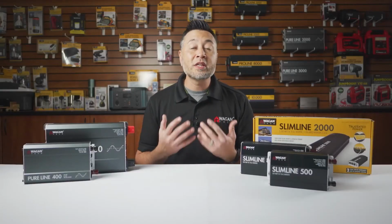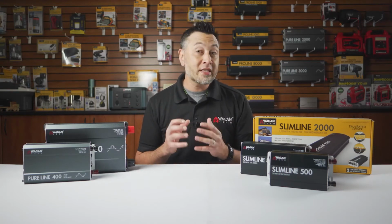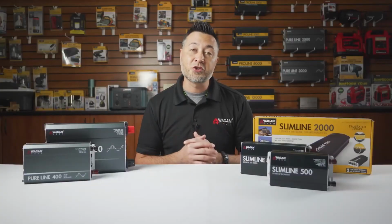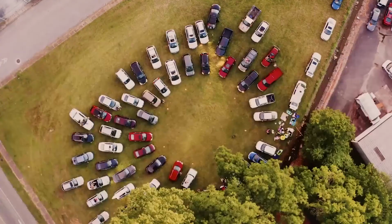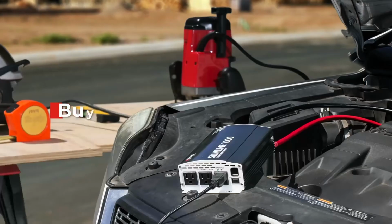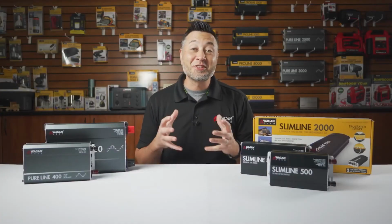So you're probably asking, what is my best choice? Well, if you are in need of an inverter that's going to power sensitive electronics, buy a pure sine wave inverter. You can't go wrong with that choice. On the other hand, if you need a temporary power solution while tailgating, camping, on a road trip, just to power your laptop, a modified sine wave inverter is a smart and affordable choice. Here's the takeaway.